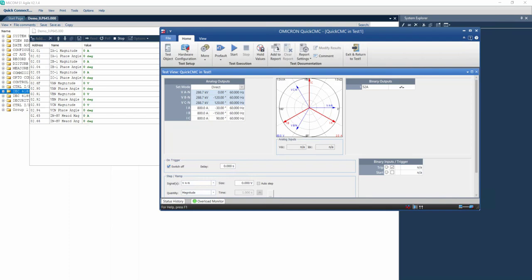Then we have introduced two important sections in the IEC 61850 standard: the sample values and the GOOSE message. The sample values are discussed in the IEC 61850-9.2, which is a component of the standard that defines how to stream high-speed dataset samples in Ethernet packets.